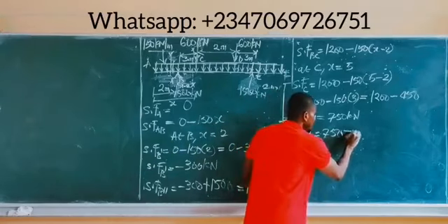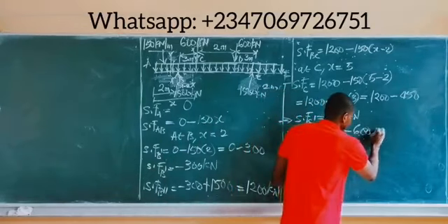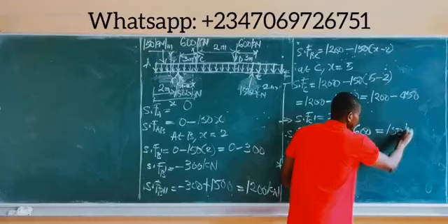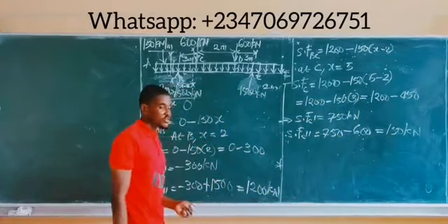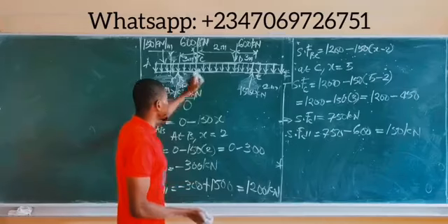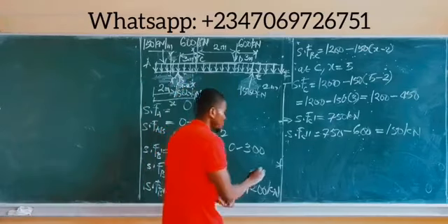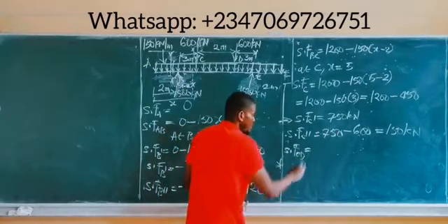So you simply have minus 600. So 750 minus 600 simply gives us 150 kilonewtons. So that's the final shear force at point C, 150 kilonewtons. Therefore, moving now along CD, this shear force along CD, this 150 kilonewtons force that we have last,